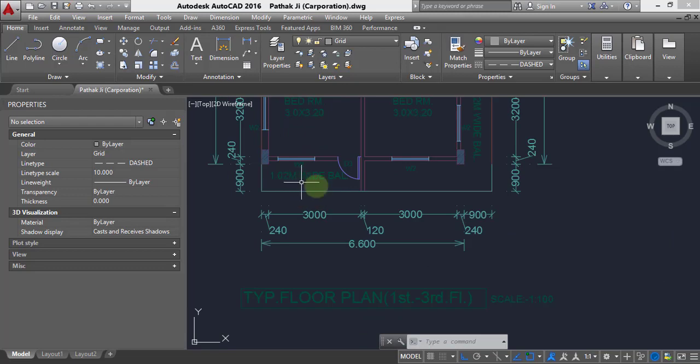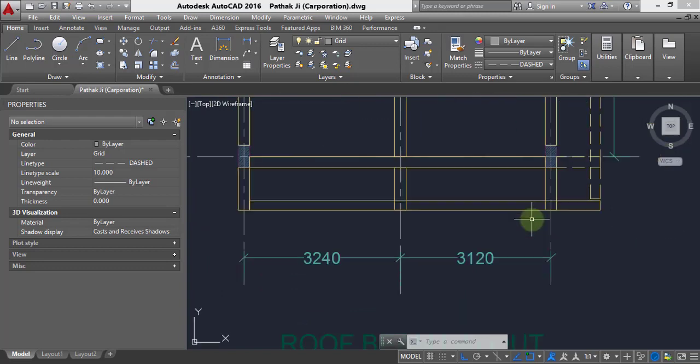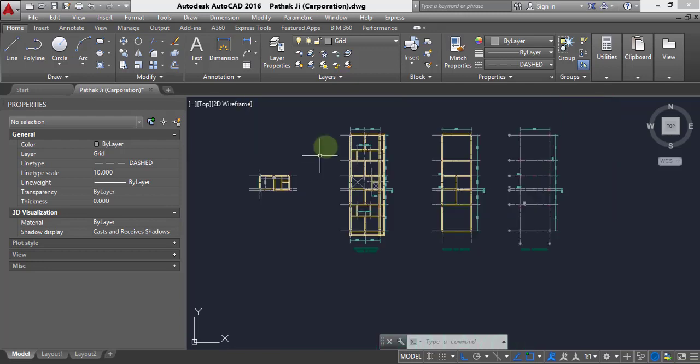If you observe, there is one balcony which is 1.02 meter wide. So to support that 1.02 meter wide balcony, here there is a periphery beam which is 200 mm wide. Okay, so this is 200 mm wide, and the depth which I'll be providing is going to be same as 450 mm. So once you complete this, actually we are ready for the geometric modeling in STAAD. So let us see how you can do the geometric modeling in STAAD.